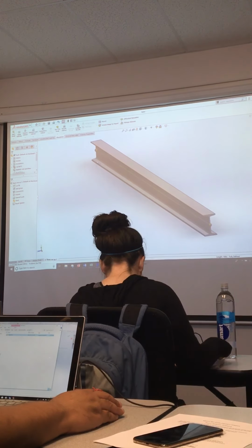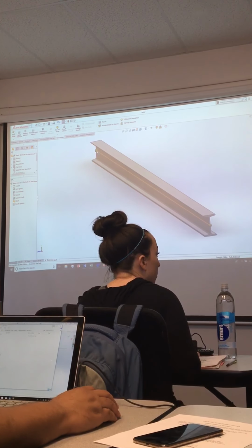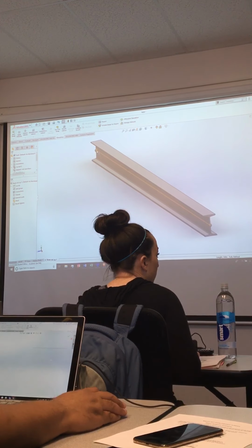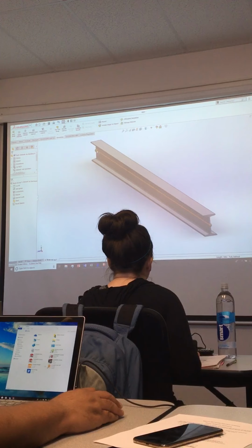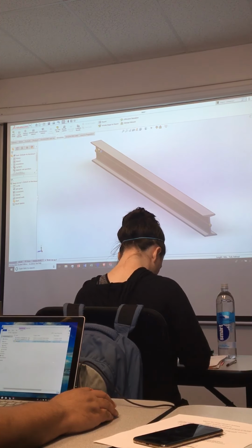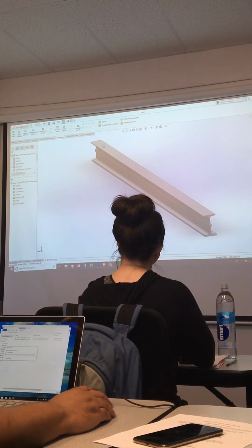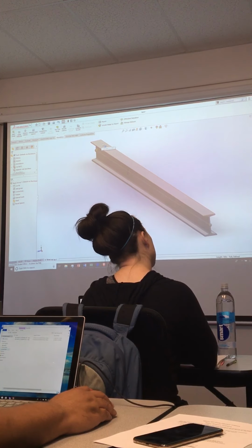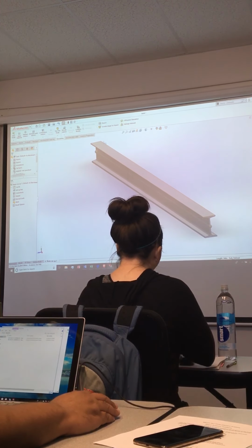Okay, so anyway, these are indications of what it calls joints. When SolidWorks makes a model out of beams, it puts joints at the ends of it. There are places where other things can join to, okay? And so it indicates where the joints are in your beam model with these balls, okay? And so this is a place where we can apply constraints to. We can apply loads to them, we can apply displacement constraints, other things.